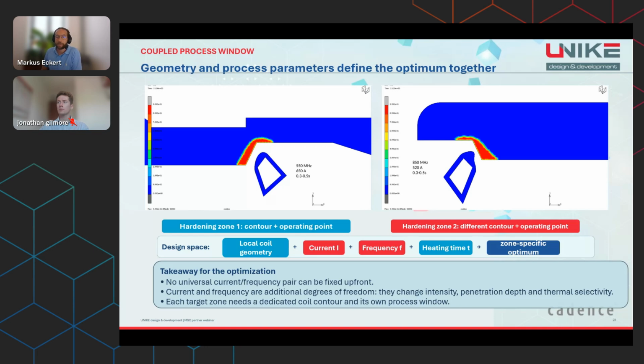In addition, current and frequency change intensity, penetration depth, magnetic force effects, and thermal selectivity. In principle, even each targeted zone therefore needs its own process window, local coil geometry plus a suitable operating point.